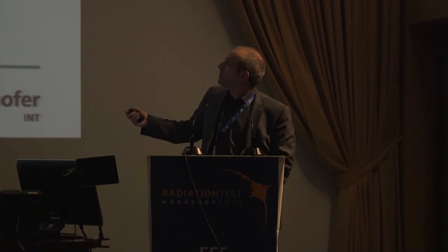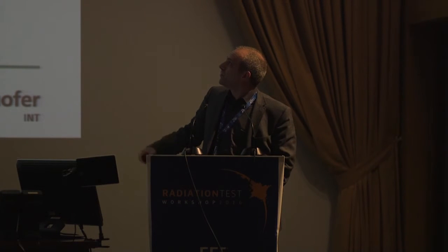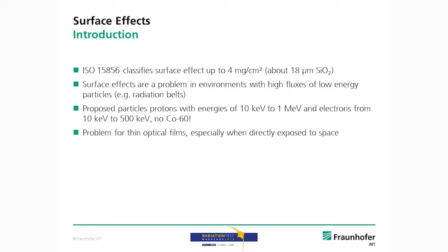Usually for bulk glasses, the way to harden glasses is to add cerium. And this number gives the weight percentage of the cerium in there. It hardens the glass significantly, but everything comes at a cost, and you buy it with a reduced transmission window in the ultraviolet usually, which you can see. The hardened glass is not as white as the non-hardened ones; this yellowish shimmer comes from the cerium addition.